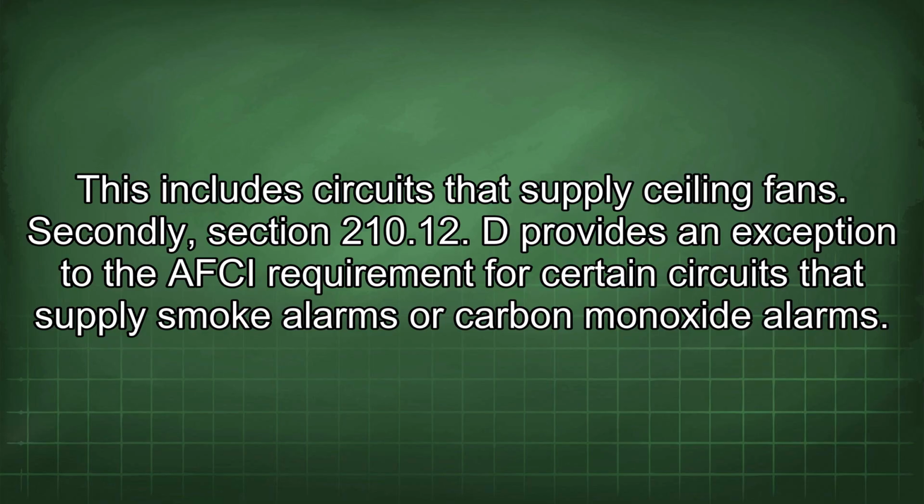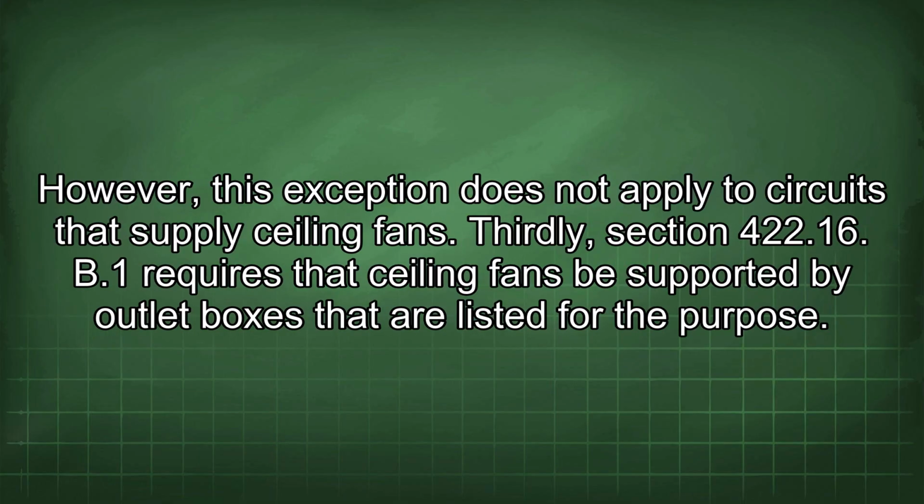Secondly, Section 210.12 provides an exception to the AFCI requirement for certain circuits that supply smoke alarms or carbon monoxide alarms. However, this exception does not apply to circuits that supply ceiling fans.